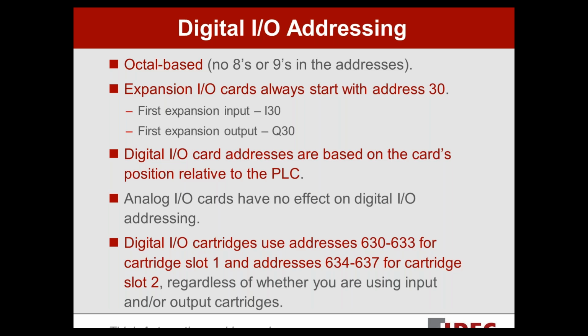One of the things that may look a little funny to you when you start using IDEC PLCs is anything that is by nature a bit, a digital input, a digital output, or even an internal relay. Those are all octal-based addressed. In other words, we don't use 8s or 9s in the addresses.